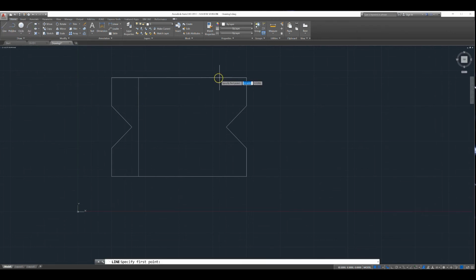If you're working on the grid the same way I am, it'll be 1 right before the darker line. Click on the line tool again. Go from the corner, 1, 2, 3, 4 spaces. Click and bring it straight down. Click on the space bar or the enter key to exit out again.